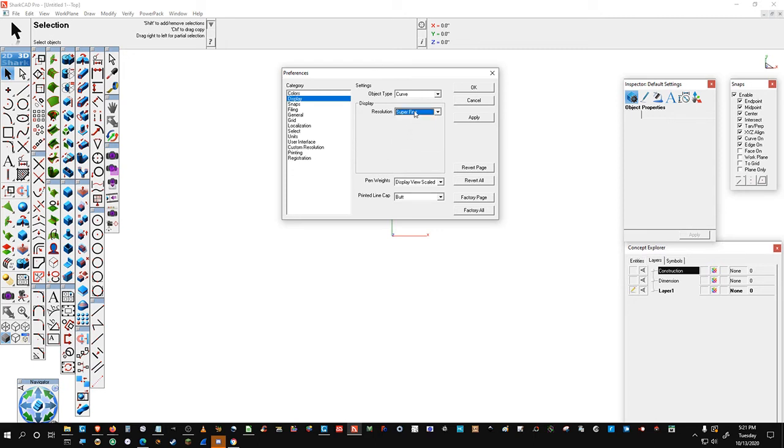Now, I will give you a piece of advice, and that is, if you're rendering a scene, put it in coarse, get all of your objects where they need to be, get your lighting just perfect, get your materials attached to everything, keep using coarse and rendering so it's real fast every time. Once you've got everything the way you want it, switch it over to Superfine and do your final output render, which would be this camera here with the little piece of paper.